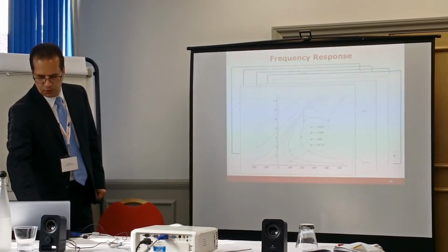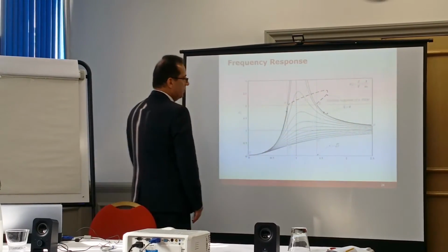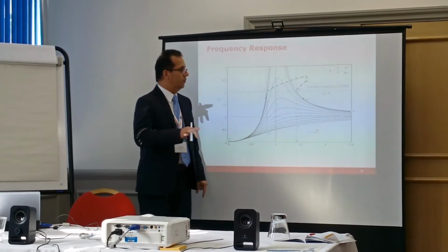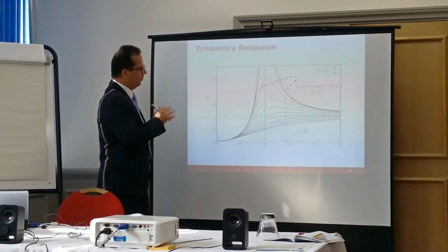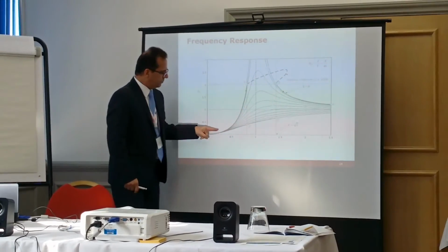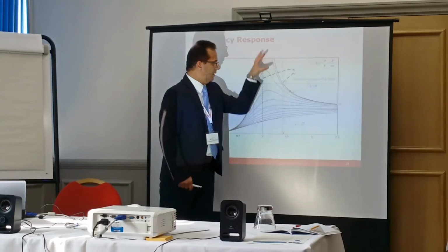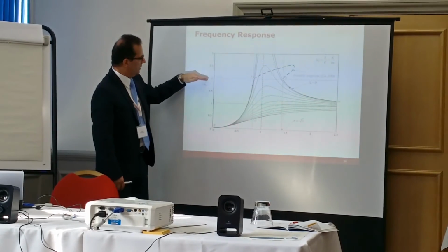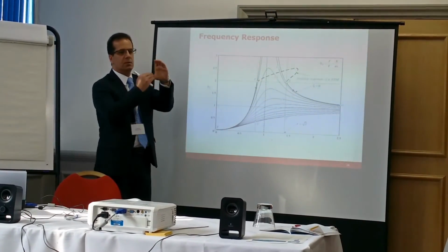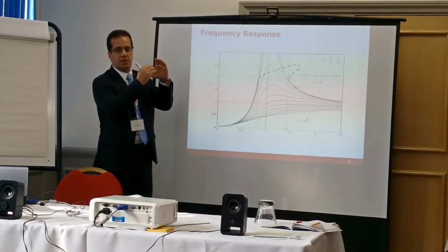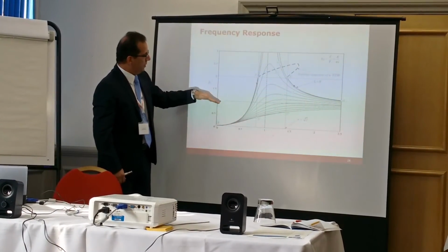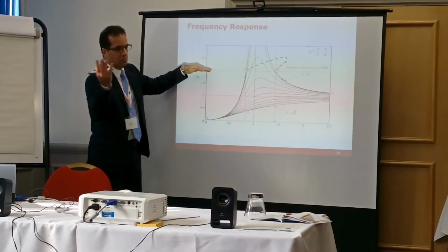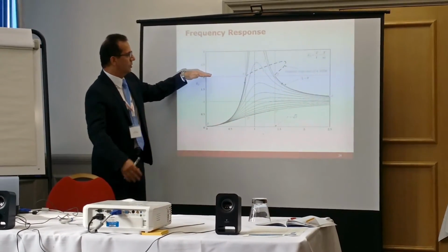This is out of our scope today, but I want to mention the difficulty of the mathematical analysis of the system: we cannot predict all the behavior of the actual system using mathematics. This is what happens. If the system was linear, the only thing that you would see is what is plotted here, and you're familiar with that. Let's assume that at this point, which in this case is 2, we have the limit, either piecewise linear or the hydraulic mount. The amplitude reaches this point, then the damping and the stiffness are going to be tripled or any order that we wish.